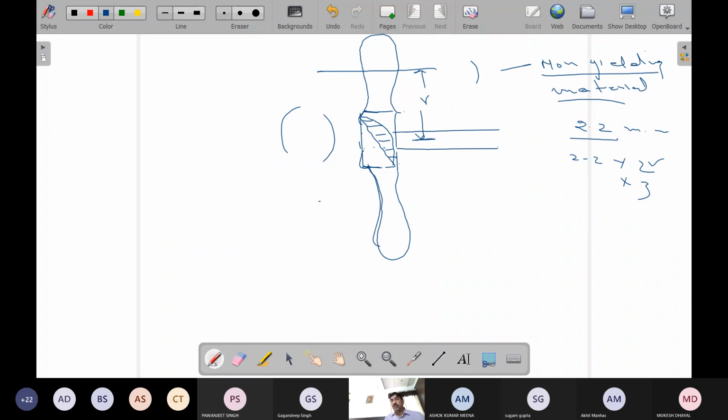This propeller also theoretically, because it is a screw propeller, the blade angle will keep varying from the root to the tip. If you have seen during taking draft, if the top part is visible, sometimes when you have a trim in such a fashion and the cargo has been discharged, the propeller tip is visible and some part of the propeller is visible. So you will see that the angle is changing from the root to the tip. It is not the same angle. So if we say that this angle is theta at a particular distance r,